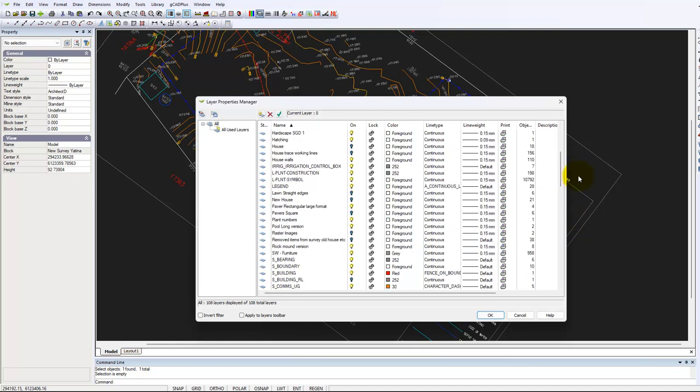That's why we use L for everything that we landscapers put into these CAD drawings. We have a layer called L construction, which is just a circle and a point in the middle for planting guide to our planting team, whereas all plant symbols go into that layer. The surveyor here is following an international standard for drafting.